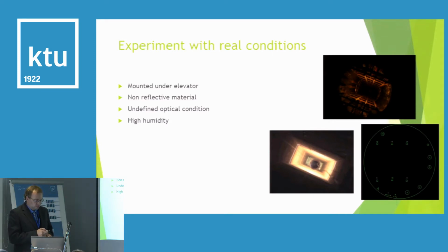But with the laser we can make a good cutting plane. Generally, a big problem is humidity and coal powder or other small particles in the air, which distort the measurement, and if you shine light on some small particle it reflects, so it's another problem with optical methods. But in single shot photogrammetry you eliminate many points because you know exactly that they are in the wrong place.